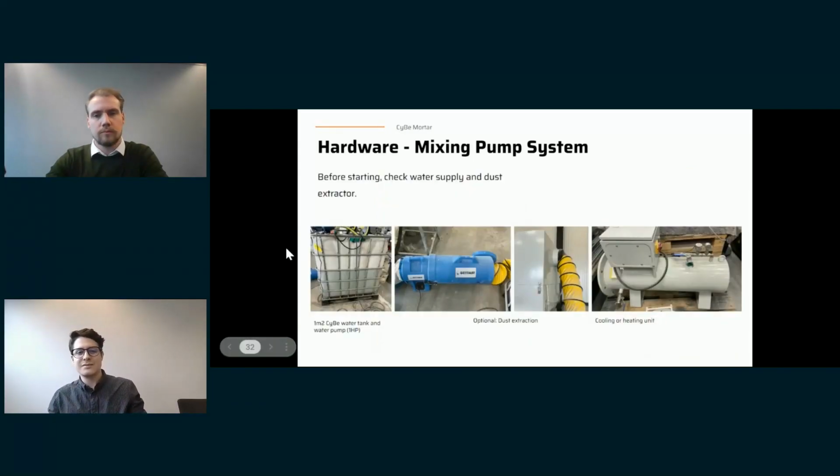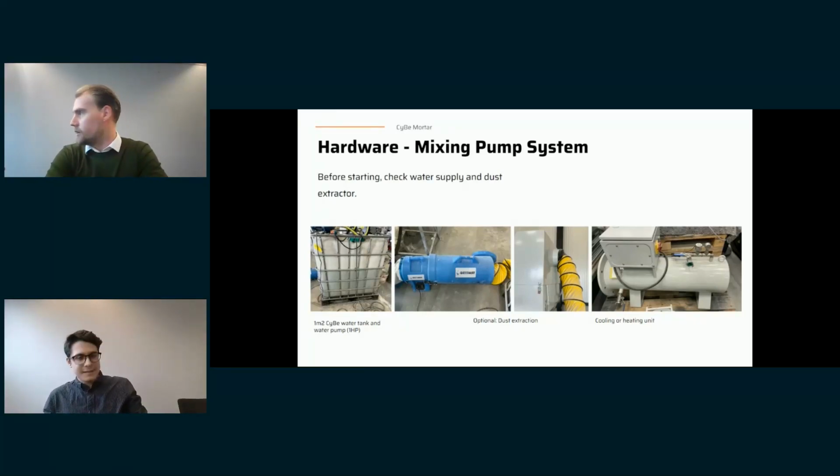Also, I think sometimes it seems obvious to say, but we try to keep the people working around the cement quite safe. Depending on the project that we are doing, we also use IBC tanks that provide a constant pressure. Normally, we go from 4 to 8 bars, but we prefer to work with 6 bars for the water pressure because it's important to have a constant pressure along the project. So that's the water that flows through the mix pump station, where it gets mixed, right?